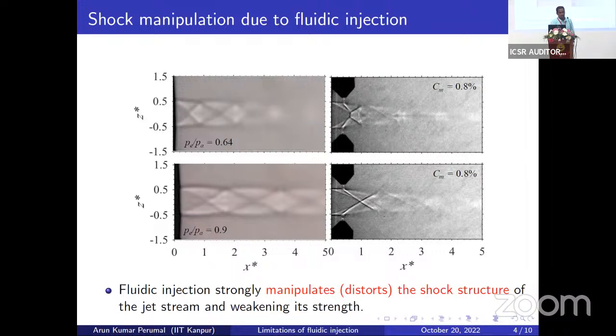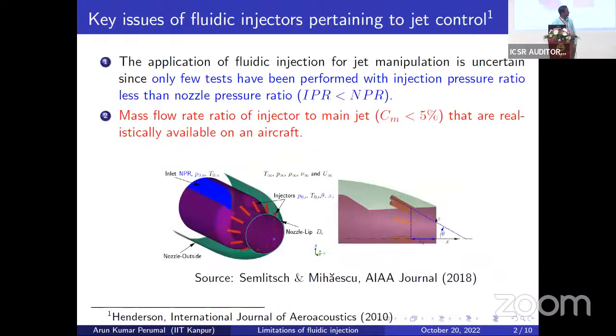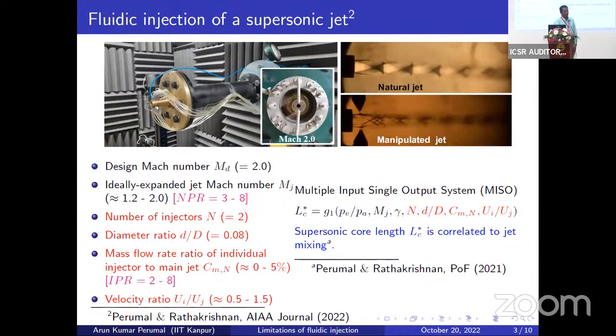We just shifted the injection slightly, because if you see the first one, if we inject somewhere over here, we would include thrust loss. There is going to be some percentage of thrust loss, and we don't want that. So we thought we'd slightly shift it and see the case without the thrust loss. The moment I inject any fluid over here, there is a percentage of thrust loss that one needs to account for. In order to avoid that, we inject downstream in the later cases. We'll look into the other cases as well.